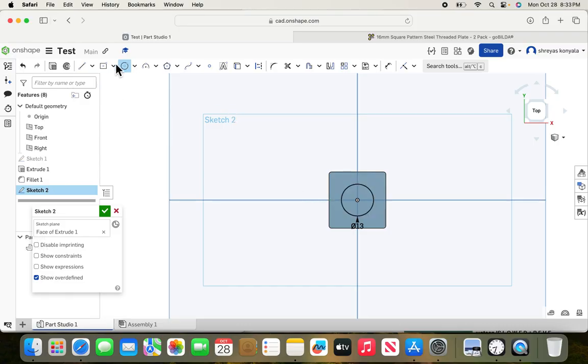Now to make life a little bit easier, let's make 4 smaller rectangles. If you want, you can just make it so it's off to the side. It really doesn't matter. And if you want, you can select the value now, or you can do it later. So for example, if you press the letter D, or you press dimension, that's right here, you can go here, press the perimeter of the circle, and do 4.